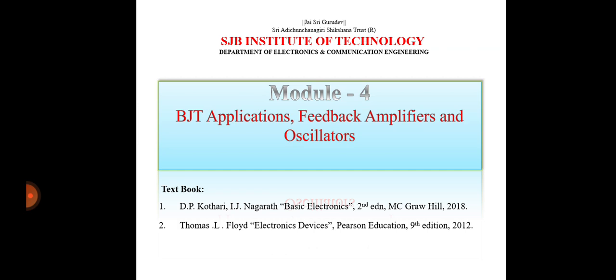And we also studied the negative feedback amplifiers, and in that, we went through a particular kind which we called the voltage series feedback amplifier. We also saw that the gain of the negative feedback amplifier gets reduced by a factor of 1 by 1 plus A beta.